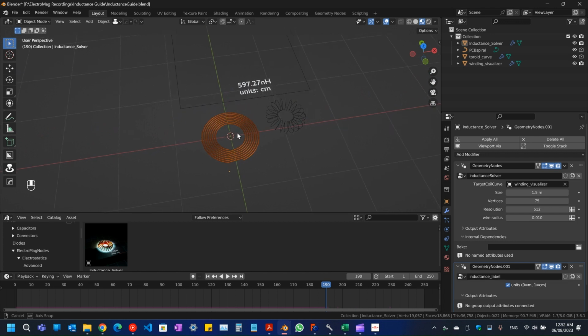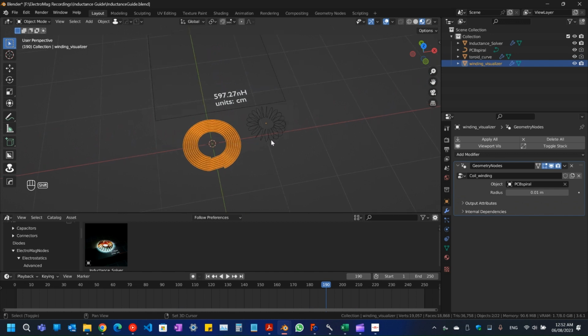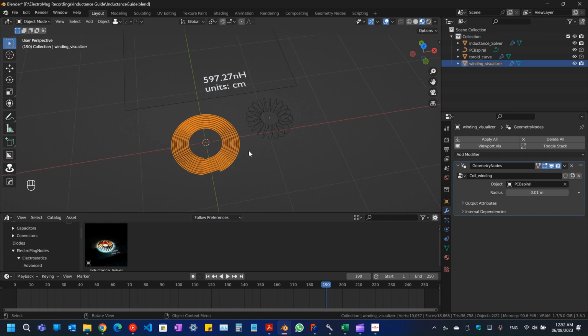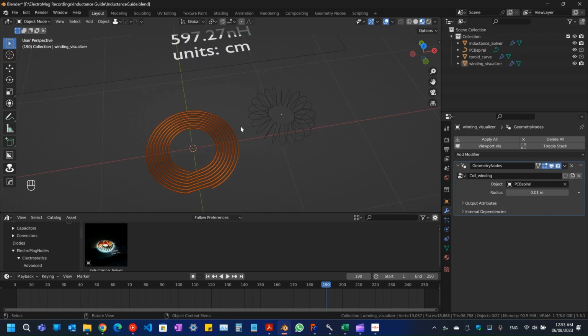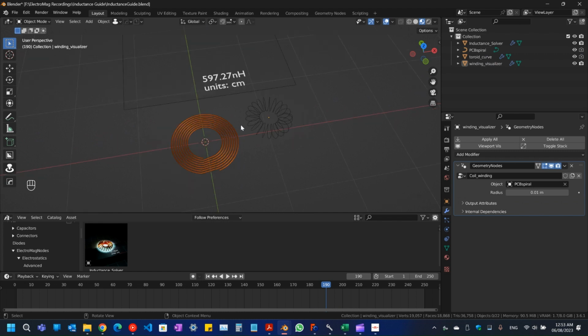And so now we've designed two coils, a toroid and a spiral, and we've compared our results with FastHenry. Now, I just want to mention that this tool is still in its early phases, and so I would not rely on this tool to design inductors. You might only use it as a starting point, as guidance, and then once you have a certain coil that you think is worth proceeding with, you then go to a professional tool to confirm your simulation results.